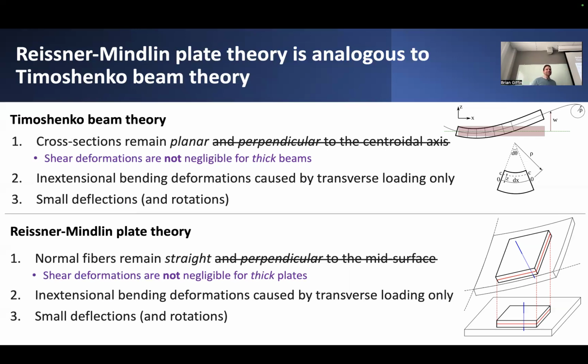If you have multiple materials comprising a beam or plate that might be layered in different structures, then the kinematics become much more complicated, and the resulting distribution of strain and stress through the depth of this beam or plate can no longer reasonably be idealized through these simplified assumptions of beam or plate theory alone. So just bear in mind that really this is all assumptions.